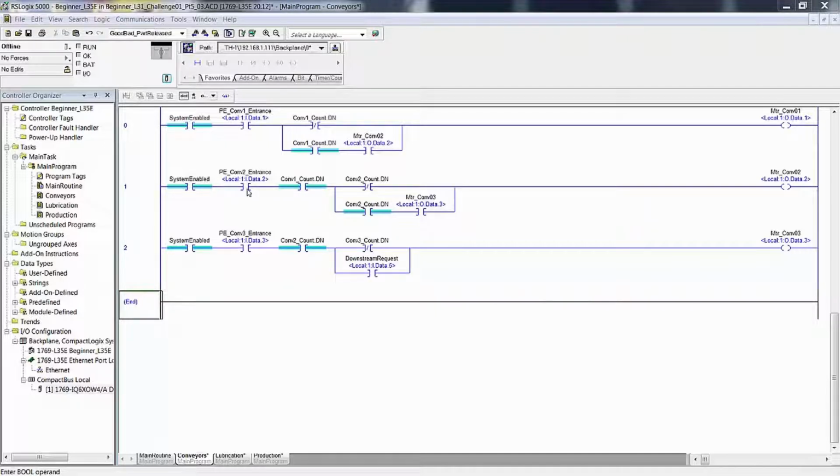We understand this, that a carton blocking the photo eye at the entrance of conveyor 2 implies indirectly that conveyor 1 is running, because conveyor 1 wouldn't run unless it was empty or conveyor 2 is running. But we're talking about getting conveyor 2 running. If conveyor 1 is running, it'll be because the motor of conveyor 2 is running. So in the case where this is full, conveyor 1's not going to run until conveyor 2 runs. But anyway, let's move on.